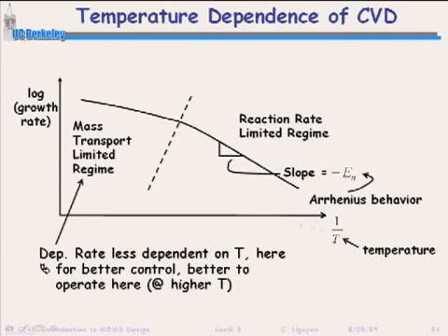And so you see this. And so usually you see a knee point here where you can then decide where you want to do your deposition, which you think you have better control of. Oftentimes you have better control of how fast you're shoving gas particles in versus the reaction rate. So oftentimes you like to do high temperature depositions so you can get a little bit better control of how fast that film is growing.